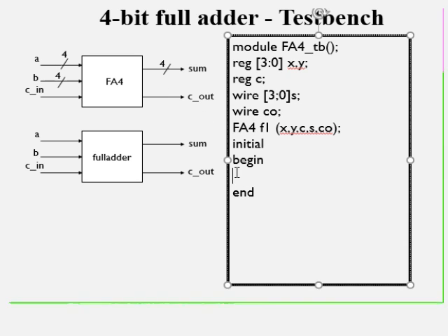So here, for my functional verification, I'll give some random numbers. I will give X as some 4-bit number, say 5. How do I give the 4-bit number? It is better for me to give it in decimal. So for a 4-bit number, the number of bits is 4, and tick D indicates that the value that follows is a decimal number. So I give it as 5. This is the first number, and the second number I will give as say 9.